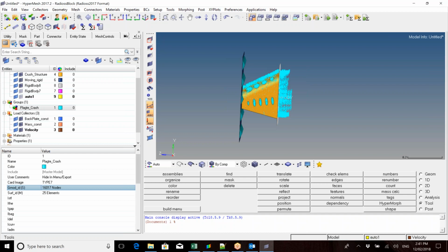So the initial penetration is a big factor, because what it automatically does is it creates a stress within the element that's not technically there. So it's a false stress, and if not monitored or handled correctly, again, it can throw the results out. So this is where we start to handle these kinds of things. So what we want to look at first is removing initial penetrations.